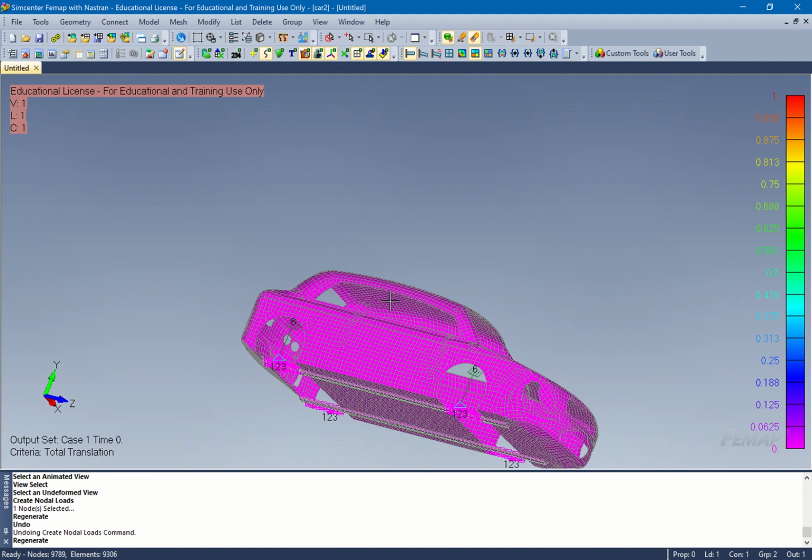That's what you have, right? Sure, sounds good. But that means nothing, right? Yeah. So I separate these two so you can actually see the spring. Got it. So we're doing it on a map. Do we have it separated, or do we have it on the same exact point? Coincident. Exact single constant. You have an infinitely small spring. Yeah, you have to have them separate to be able to apply the springs and loads.